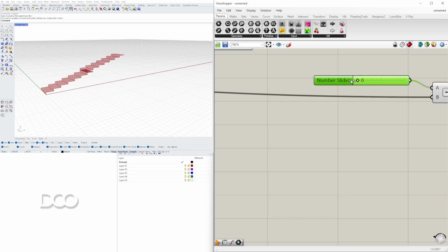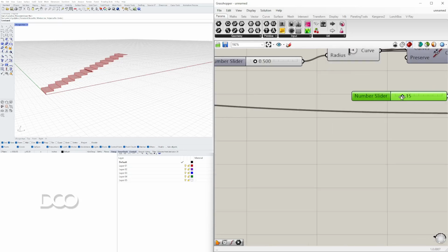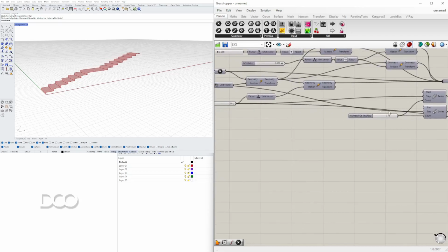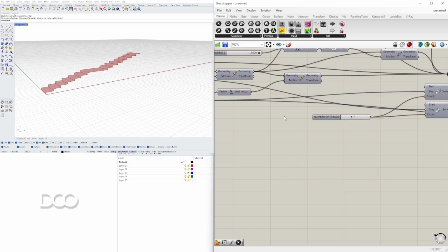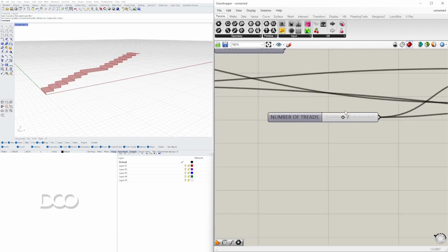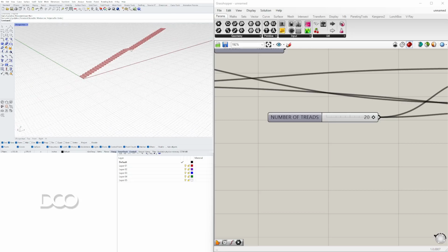This shows you zero landing. The same, this would be matching the tread, and then here is where you would add more. To be realistic, the maximum treads that you could have are 20. Because, like I said, tying it back to reality and back to architecture, technically you can have 20 treads before you need a landing.